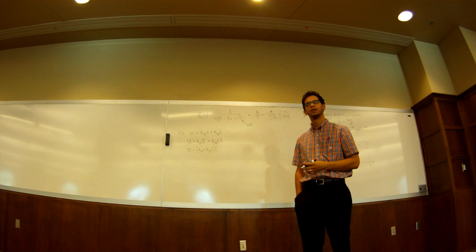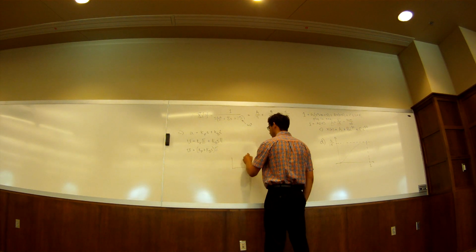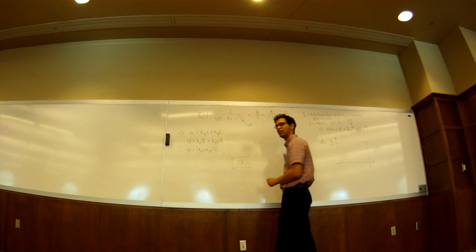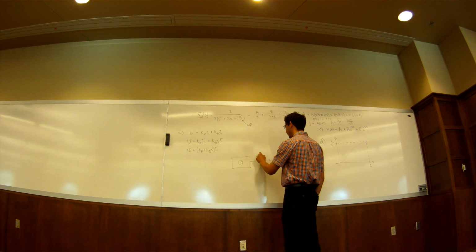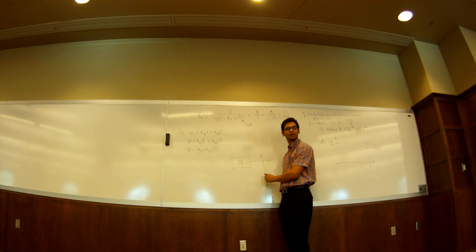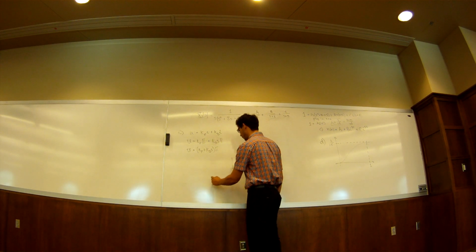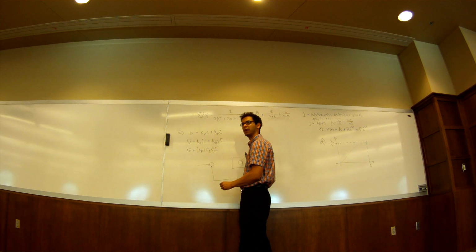How does that look? All right, so if I write this in block diagram form, I'm going to put my plant here at G. I said there was unity feedback, right? Yes. So I know that my output is going to be Y, and I'm going to feed that back. It was unity, so there's no sensor. Correct. And then I'm going to bring this up and compare it to some input, say R.